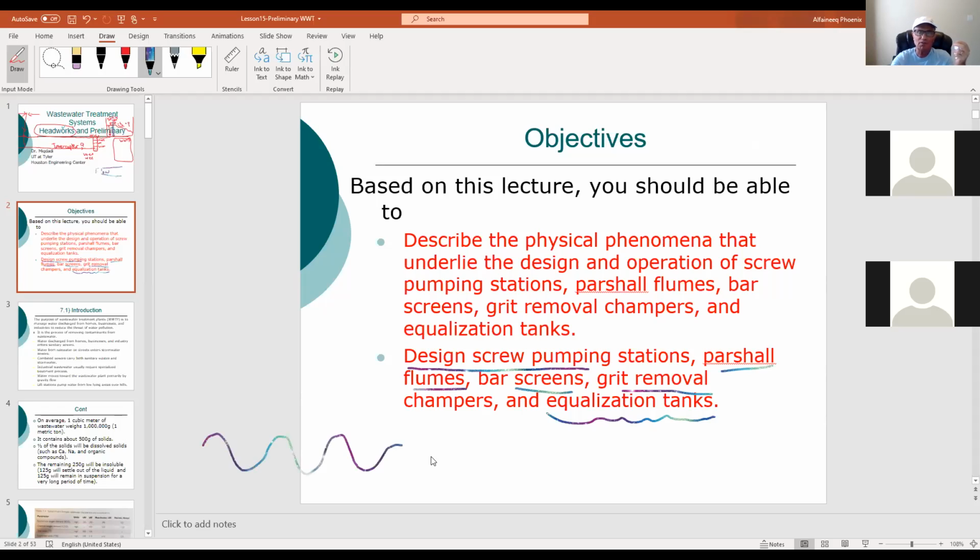So you need this equalization tank here, all right, to store water that is exceeded. And from here, you go constant Q. See, straight line, constant. And this happens, you cut this fluctuation in this equalization tank.